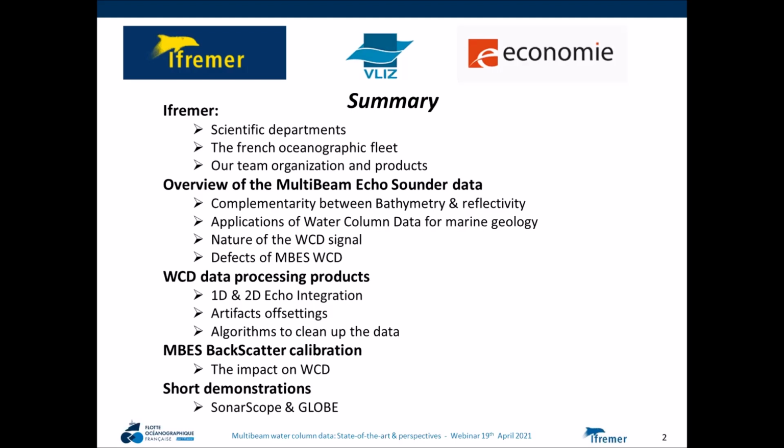I will describe the numerous defects of the Multibeam Ecosounder data, so water columns, the artifacts, the transmission sector variable gains, the change of levels when the sound modes change, and so on. I will describe some water column data reflectivity processing, such as the eco-integration, the automatic removal of some artifacts, and so on.